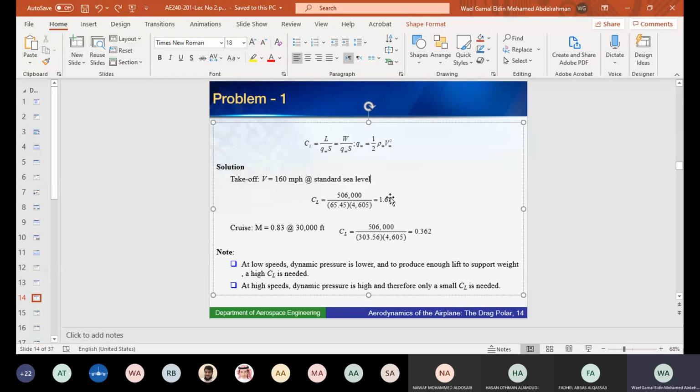They should be just at the top of your mind. It's like when you talk about speeds of cars, you are experts in this. You know that 40 kilometers per hour is too slow for a car. You know that 300 kilometers per hour is very high for an ordinary car. So you know that the maximum speed of an ordinary car is between 150 and 240. You know that range, right? I want you to start to develop that capability for aerodynamic numbers. Reasonable value for CL during takeoff, somewhere between 1.5 and 2.5, maybe 3.